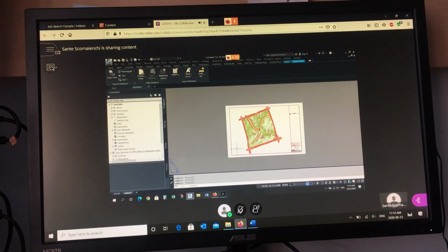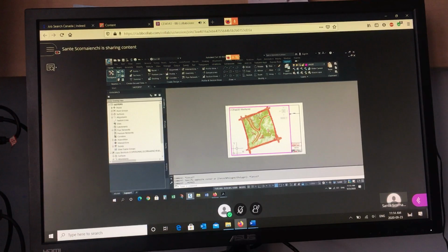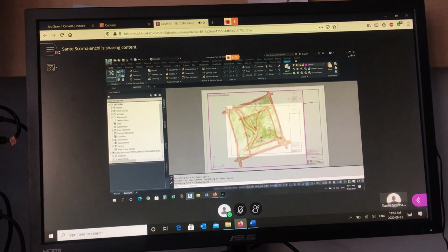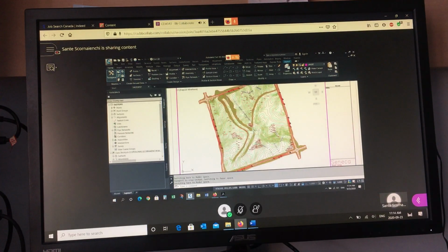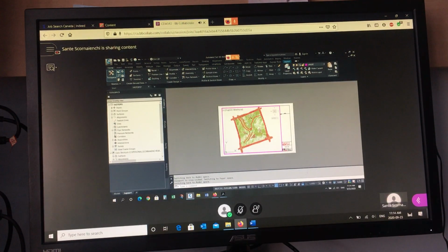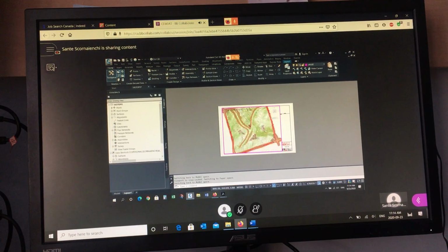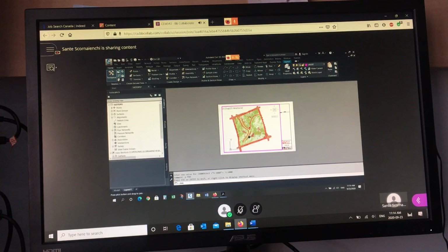So now if I go into paper space, if I zoom in and out using the middle button, the wheel on my mouse, it zooms paper space, not model space. If I unlock this and I zoom in and out, it screws up the view scale. Right? So once you have that locked, let me set it back to 2000. And let me pan over and center it.